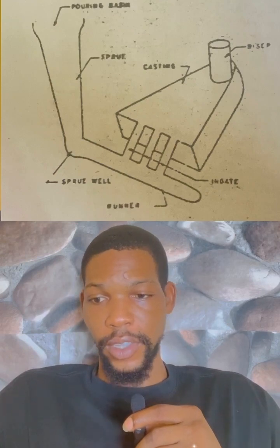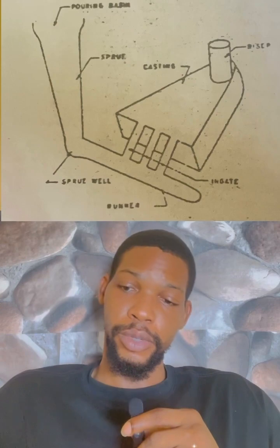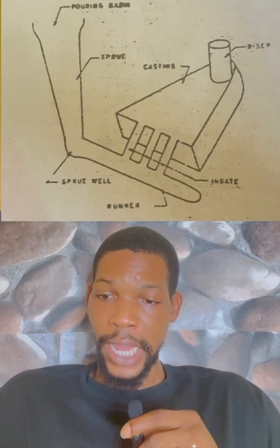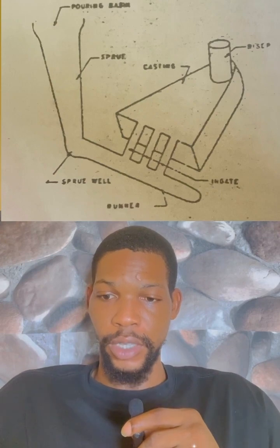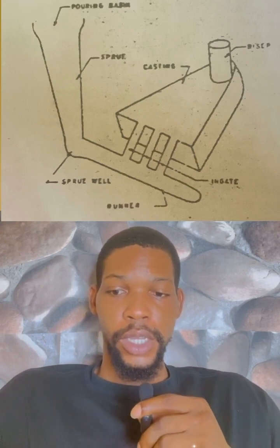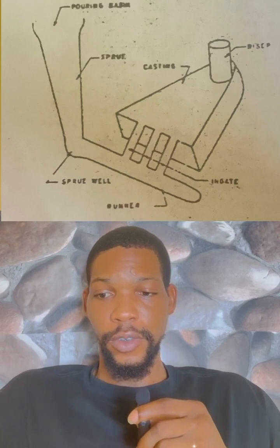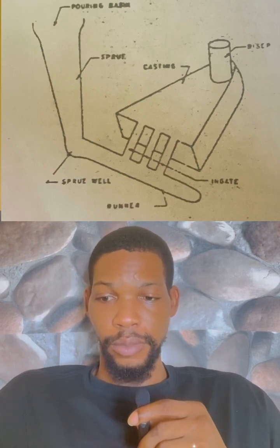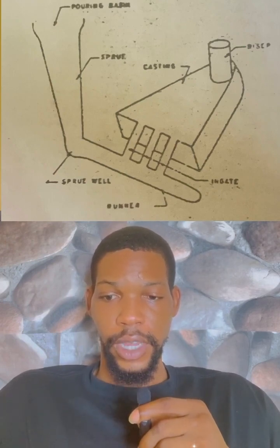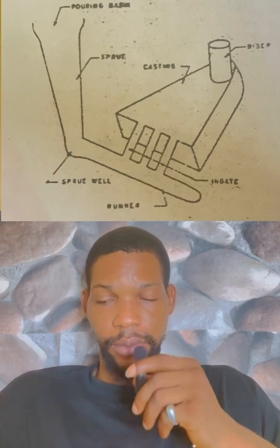The most important aspects of the cup or basin design are: one, they must be large enough so that the gating system can be choked rapidly and maintained full. They must be deep enough to permit vortex formation, and they must be placed in a location such that the ladle can be brought near to it and the metal poured in steadily without turbulence.